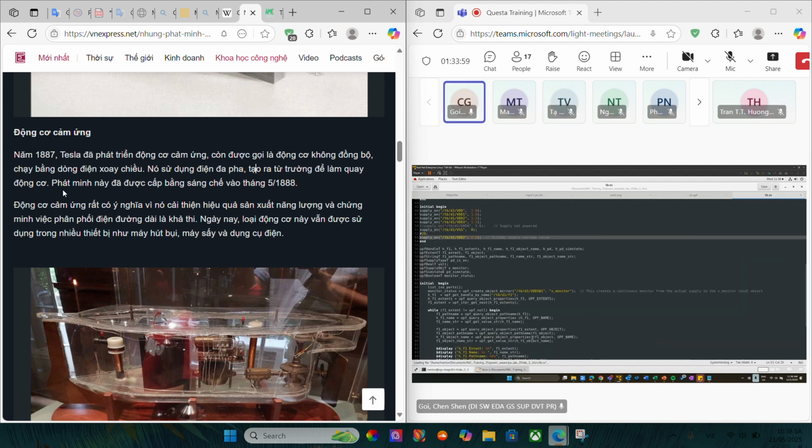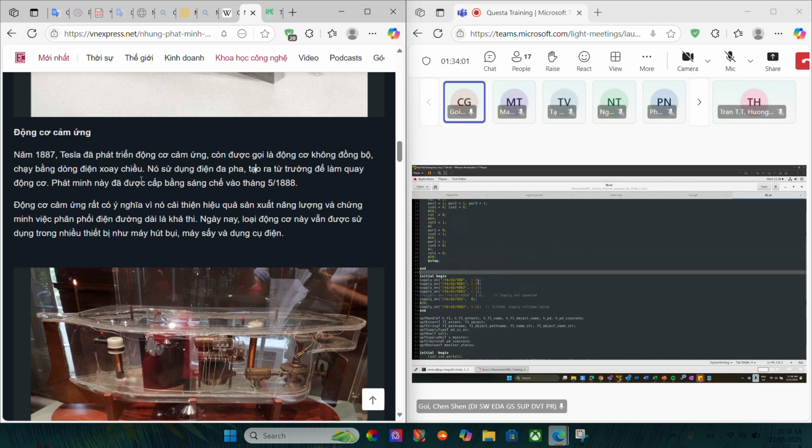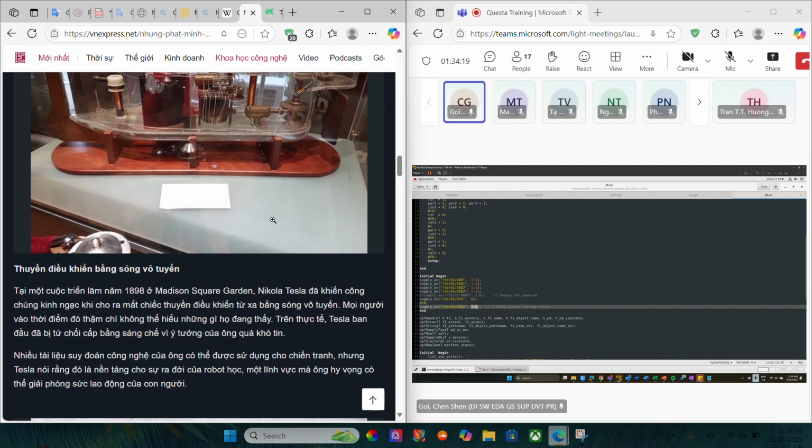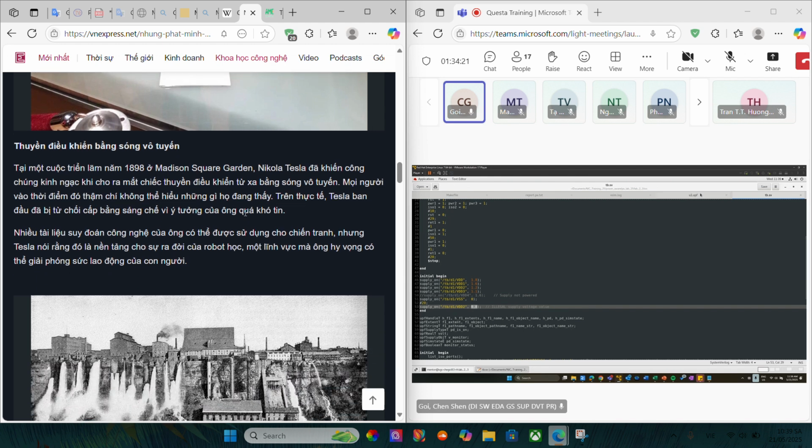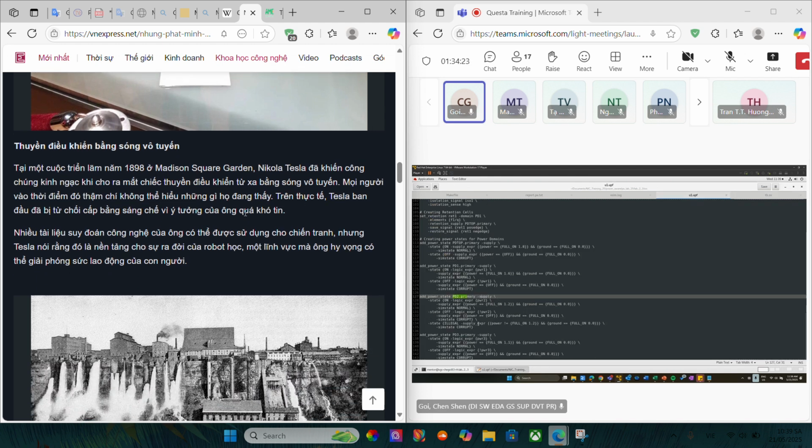So at test bench, we can see supply on for VDD2. Because we know from the error message, the timestamp is 20 nanosecond. So if we see from the initial block, right after 20 nanosecond, the supply on given to VDD2 is 0.8. So anything outside of what we specify in the state table, anything outside of 1.2, we will get error.